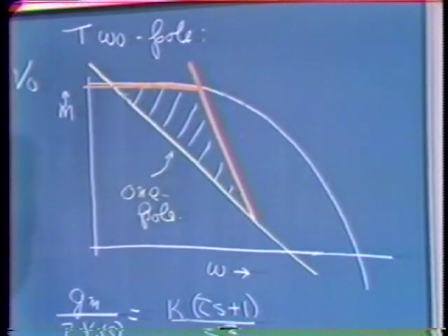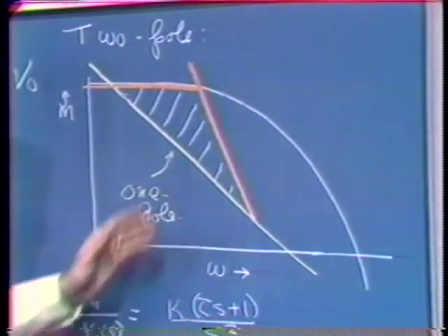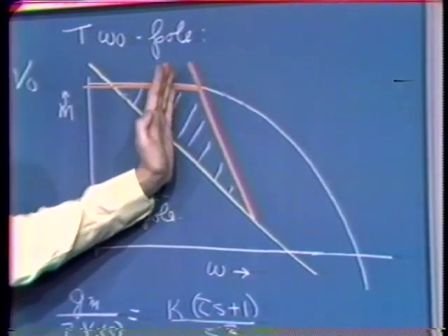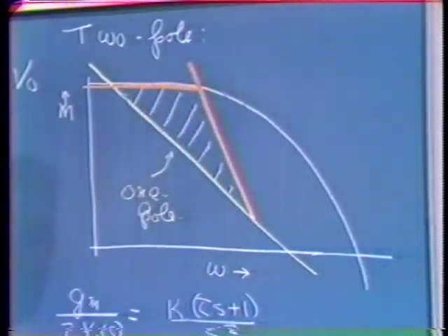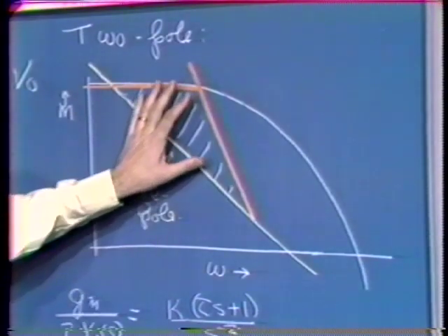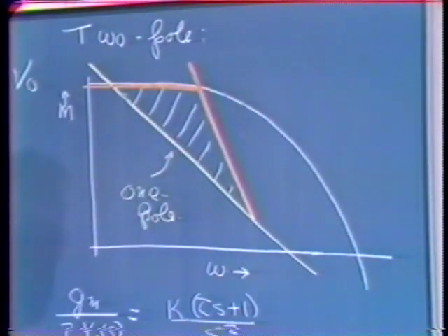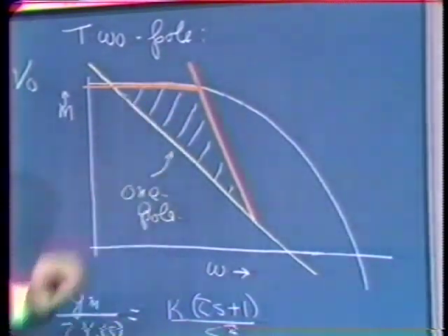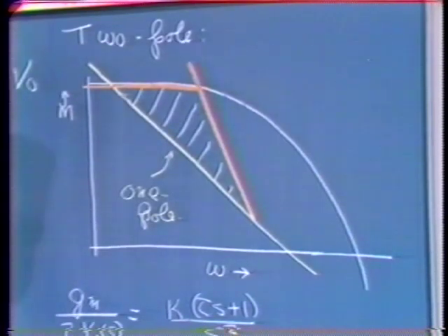The triangle wave that we've chosen happens to be one like that, where the 5 kilohertz fundamental and the appropriate harmonics, or most of them, lie in this region. We get greatly improved desensitivity, a much smaller error signal in the system. In fact, we haven't particularly cheated by picking a particularly fortunate test signal.